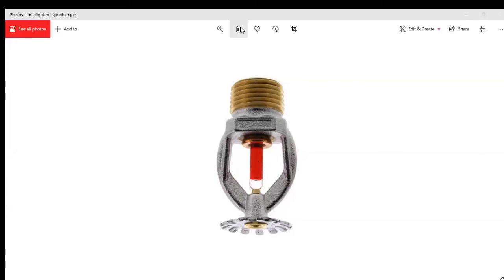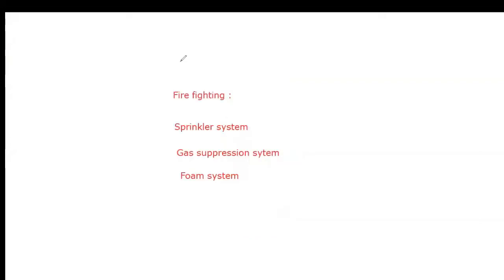That's the reason I told you we need to consider some of the standards related to this, as we have ASHRAE and ISHRAE for HVAC, NEC and IS for electrical, and IPC, UPC, NPC and NBC for plumbing. Here also we have a regulating authority, named NFPA, the National Fire Protection Association. Here in India, we make use of NFPA 13. Sorry, 13 is a chapter. Most generally, we will be using the NFPA. In the firefighting system, we will have three different categories. One is the sprinkler system, the second is the gas suppression system, and the third is the foam system.